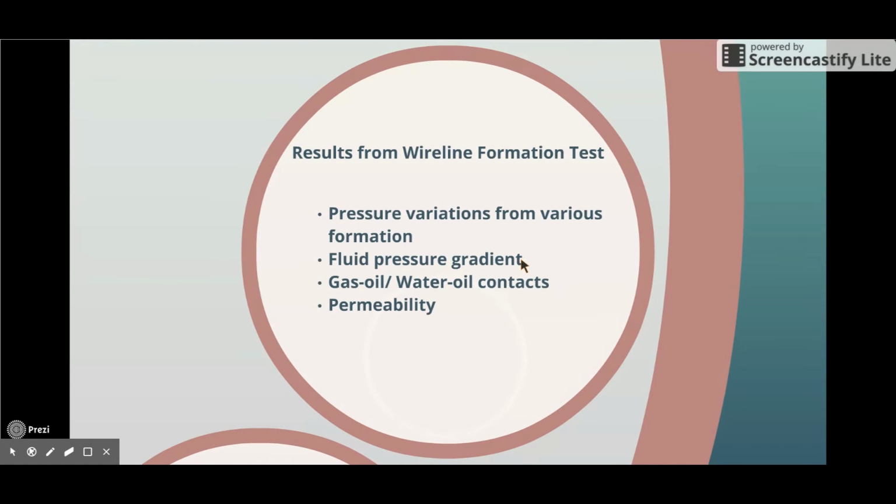Wireline formation test will allow you to obtain four results. Firstly, the pressure variation from various formations. Secondly, fluid pressure gradient. Thirdly, gas-oil or water-oil contact. And fourthly, permeability of a reservoir.